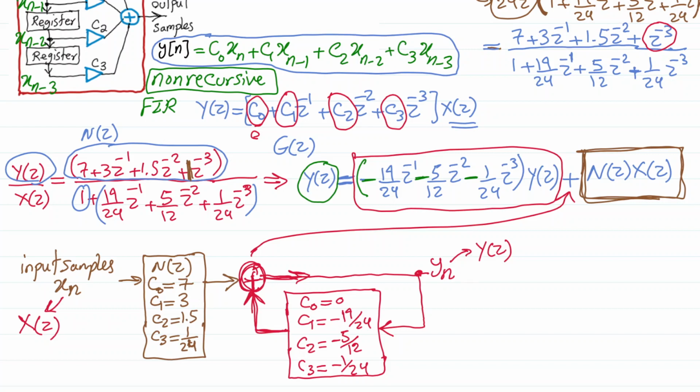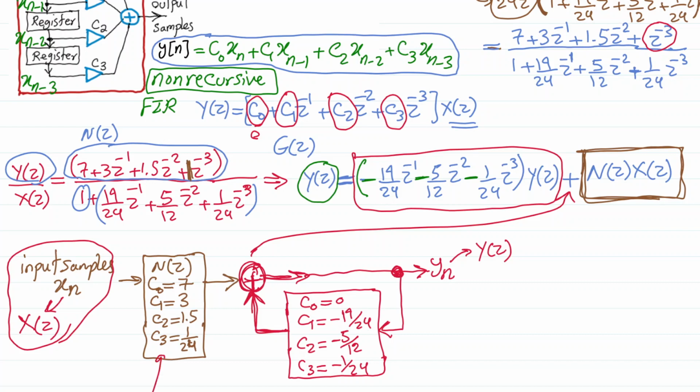So let me just shift this whole thing so that it is clear. There you go. Okay, so this output that I got is the final output that I need. It goes out. Therefore, the scheme is: input samples are coming in, entering the first chip with these C0, C1, C2, C3 coefficients that I am showing.